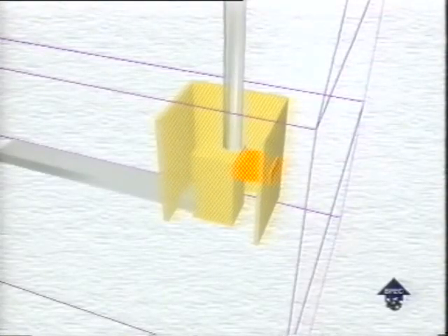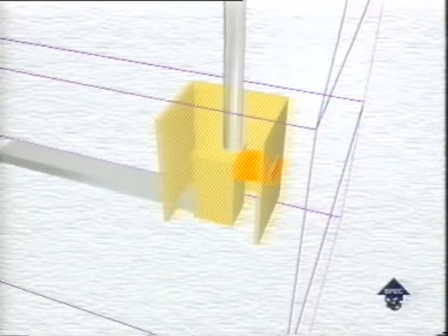If the heating unit is located in a compartment, it's important to fit a sealed duct from the return air grill to the heater. If you don't, air could be drawn from the compartment and stop the flue working properly.